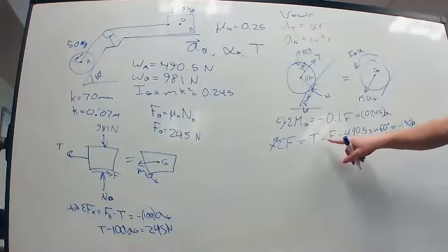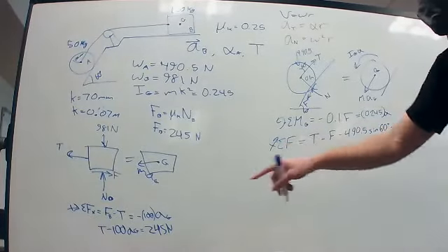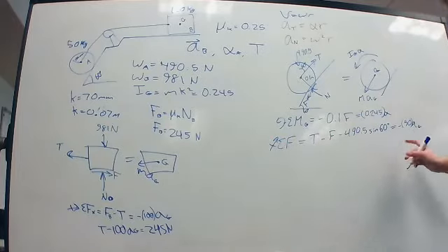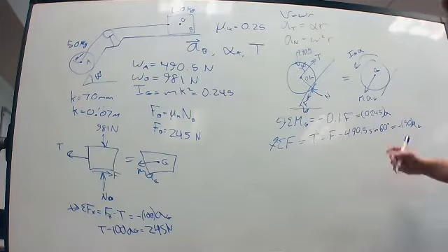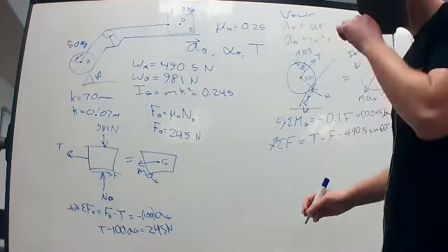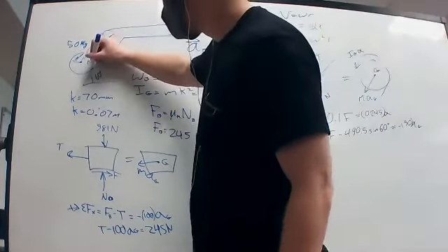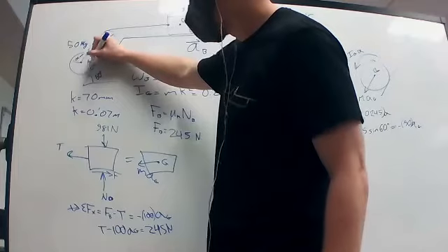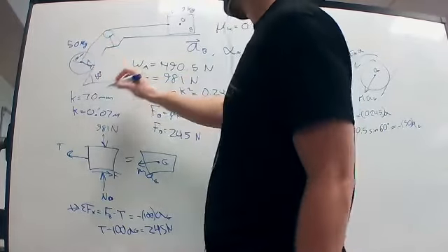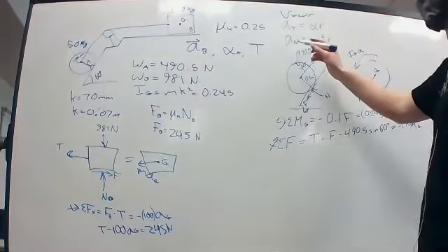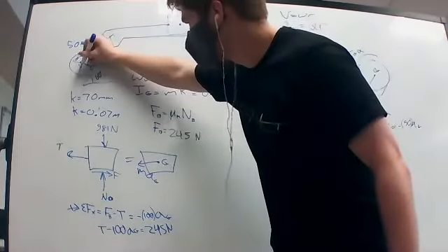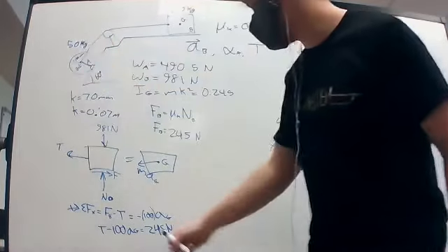We have this second equation and a third equation where T is the same from here to here. These F values are the same, so that's two unknowns. And then we have AG and alpha. We can express AG in terms of alpha because in this wheel, AG of the wheel is equal to alpha R, because this acceleration here would be AT, which is the acceleration AG.